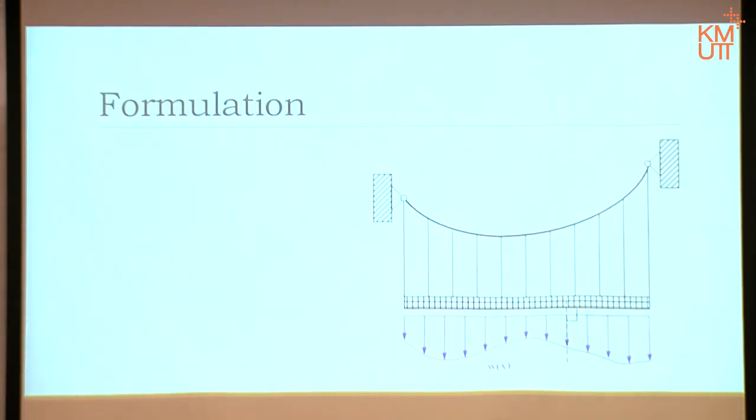You look at bridges like the Lamanai Bridge: the main cable is always a curve, not segmental straight lines. So we will treat it as a curve. The idea is that if you put the suspenders closely enough, the whole distributed load seems to go up to the cable itself.